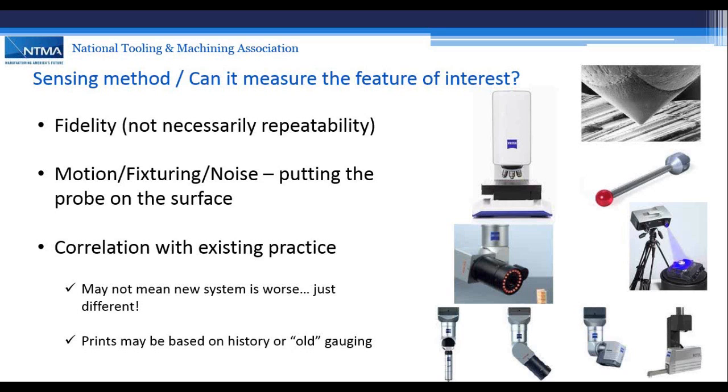Right. It's things like resolution, but also something like frequency response. If you're to buy a stereo system, you want to be able to listen to all the high notes and the low notes. Correct. So buying a measuring system is just like buying home audio. We're not necessarily going to buy home audio based on repeatability. We're going to buy our home audio based on, does it sound really awesome? Sound good, right. So when we buy a gauging system, particularly when we measure shape, whether it's roundness, flatness, roughness, we want a gauge that can sense those subtle variations in shape.